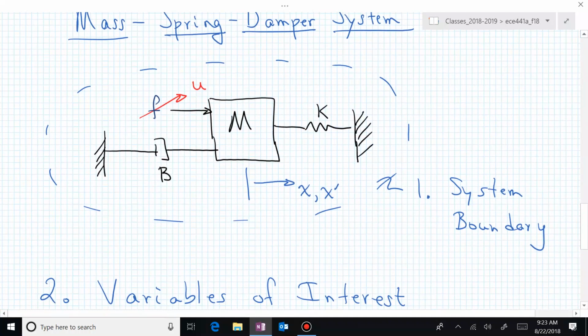It depends on how you think about dynamics and writing the equations. I like to actually now introduce another force called the inertial force that opposes movement of that mass. And then I don't get bogged down with saying sum of forces equal mass times acceleration. I can just sum all of my forces and say it's all taken care of because I've included the inertial force. In this case, if I tried to move that mass to the right, is there some inertia opposing that movement?